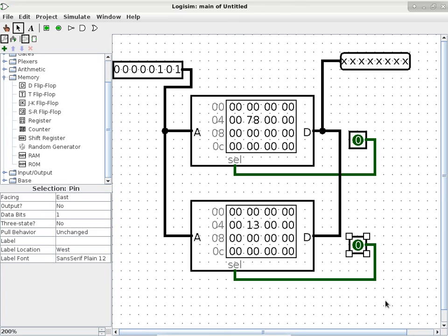What each port is responsible for? Okay? All right, so let's just say that we want to access location 5, and the first chip has location 0 to location 255. The second chip has location 256 to 511. Because that's how you can get a larger memory space when each chip only has 256 locations. Is that making any sense? Sort of? Okay? I'll use an analogy later on. So if I want just location 5, that means I want to talk to the first chip, the top one, and then just say, hey, top chip, pay attention now.